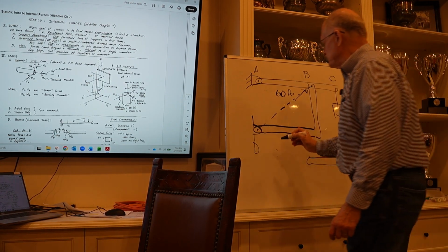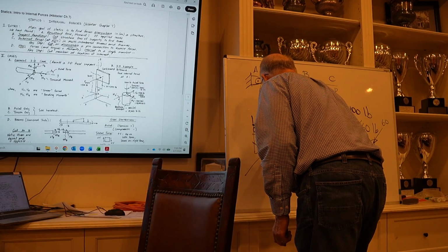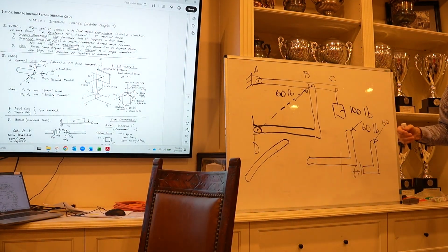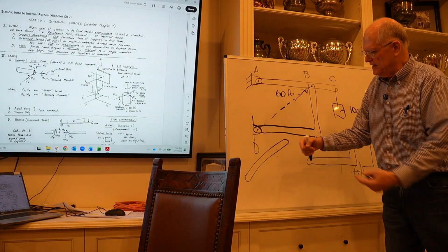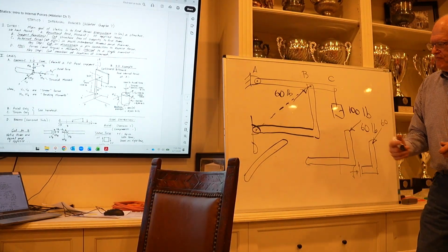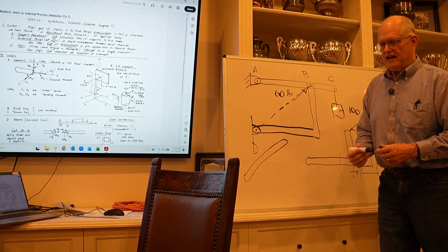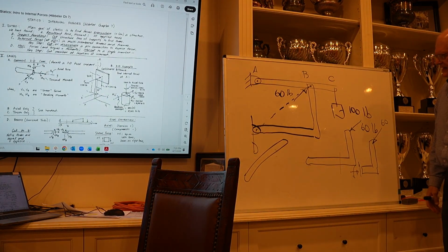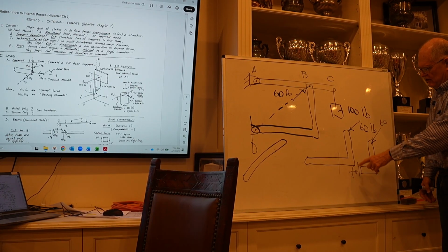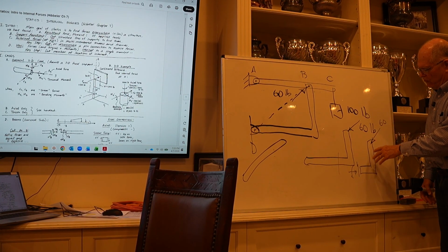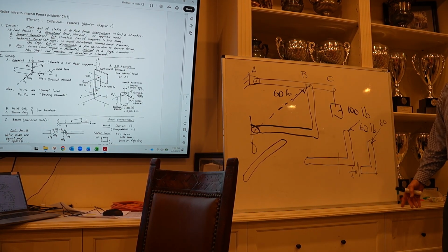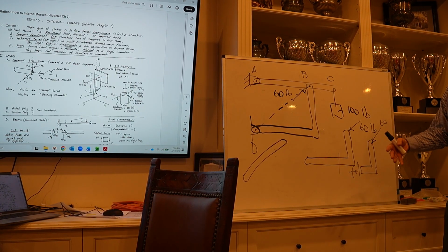If we would have put a straight 2-force member here, then it's just in compression or in tension, and the only internal force in this guy is just an axial force. There's no shear, there's no bending moment. So there's no tendency of this guy to bend. Now he might buckle. If that load is large enough, he could buckle, but that's not the bending case. But with an L-shaped guy, with this off-centered force, you can end up with axial, shear, and bending. And so you have to design this L-shaped member appropriately to manage its bending and shear.